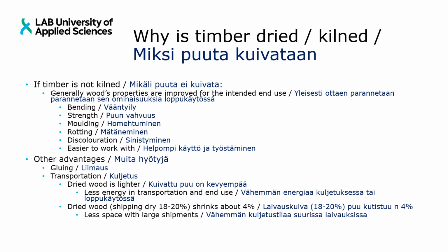So why is timber then dried or kilned, as the term goes? Well, I think the most important thing to remember is that we are improving the wood's properties for the intended use. We are obviously also speeding up the process, because in the old days, the timber could have been air dried over the winter. And now we are talking about a period usually between 3 to 4 days maybe. So you are generally improving the properties of the timber as well.